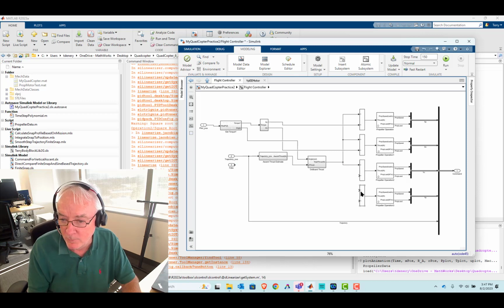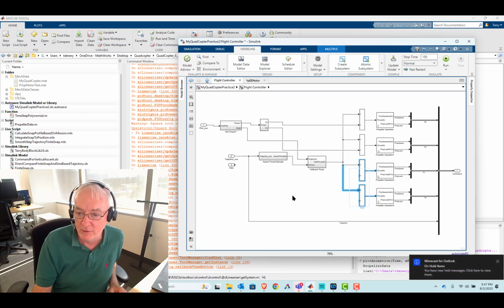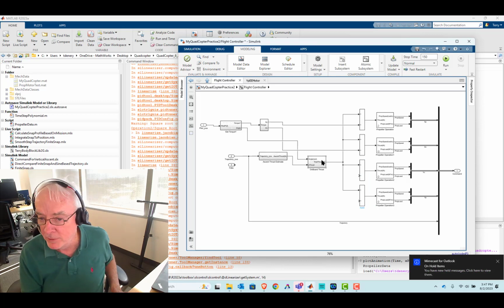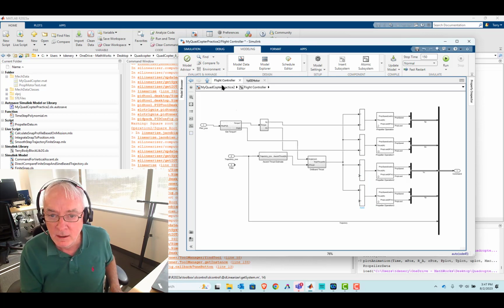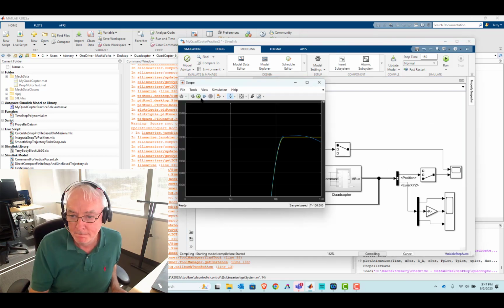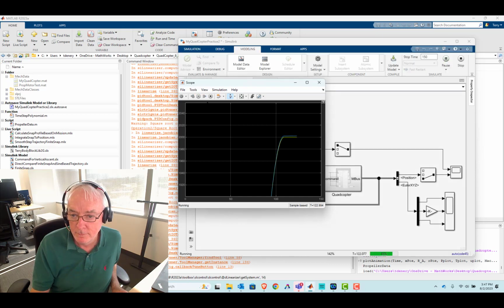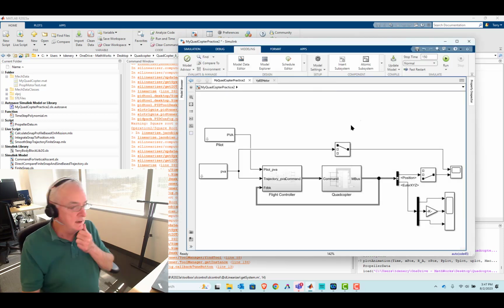And we're not doing anything with the X rotation because it's pretty much the same thing as the Y rotation. Of course, Y rotations occur through X thrusters, where X rotations would occur through Y thrusters. But I think we got it set up properly with that now. And well, let's find out. Let's run this one more time. Isn't that cool?